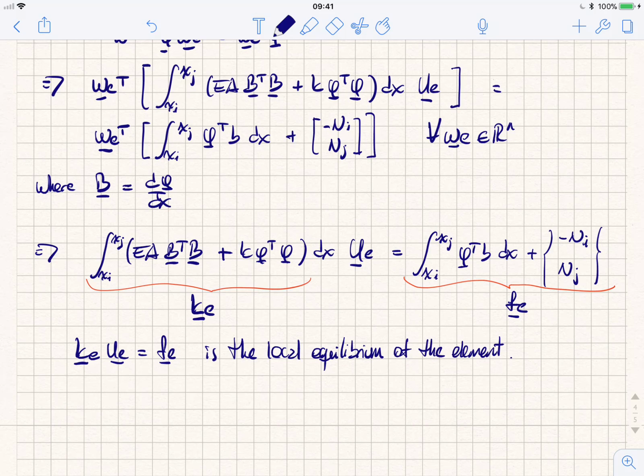Now, of course, you would expect that this doesn't say anything yet. We were just doing equilibrium in one element. So that doesn't take us to the real behavior of the whole bar. But if you do the same in the contiguous element and so on, you get a bunch of expressions that are going to give you the local arrays for each element.